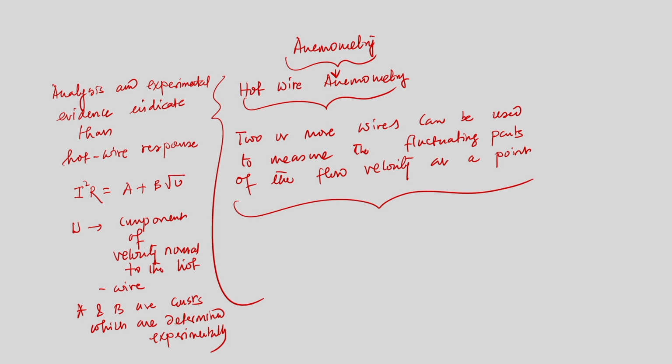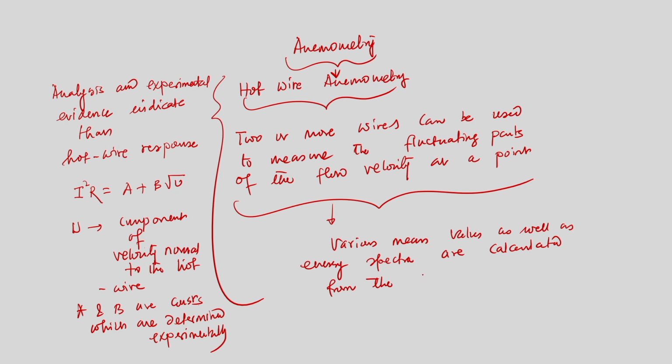Now, the question is, if you use this hot wire anemometry, of course the various mean values as well as energy spectra are calculated from the voltage output of the instrument probes.